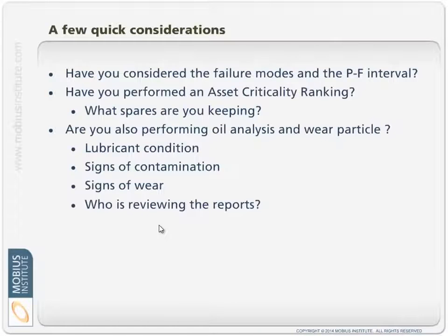So a few other quick points I'll make. Number one, you do have to understand the failure modes, as I just mentioned, but also you need an idea of the PF interval. That is basically the time between when you can detect the fault with any technique, and the time when it has functionally failed, which may be catastrophic failure, but it may be a point before that where you are basically forced to stop running that gearbox because it can no longer perform the function that it's intended to perform.